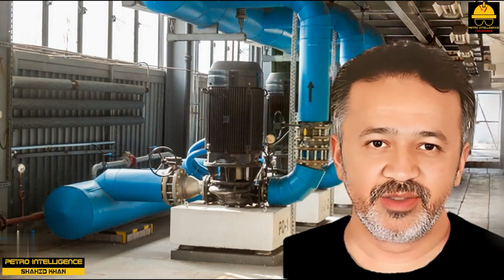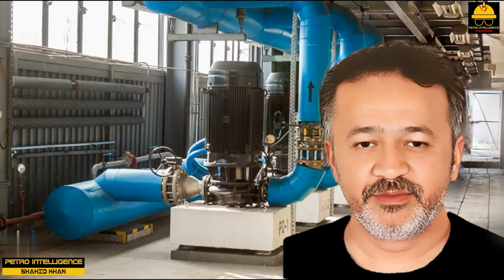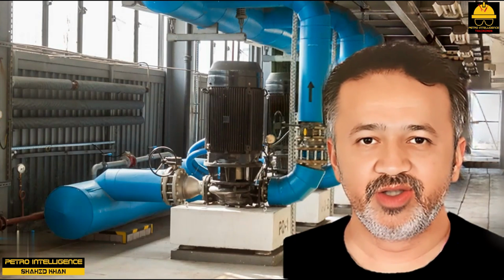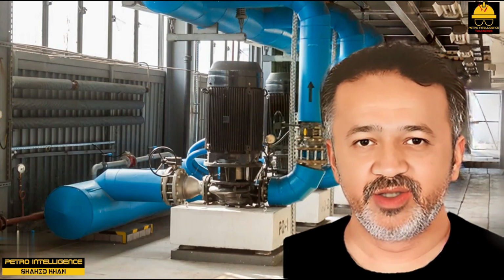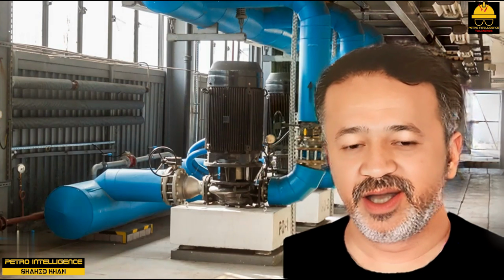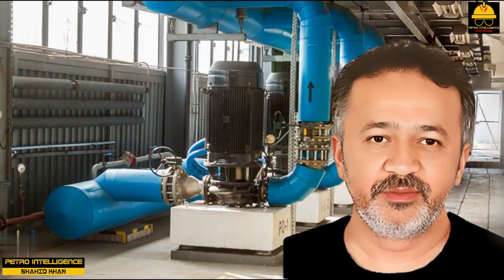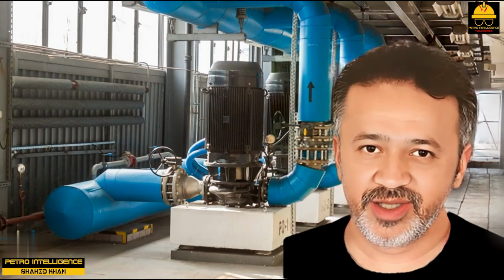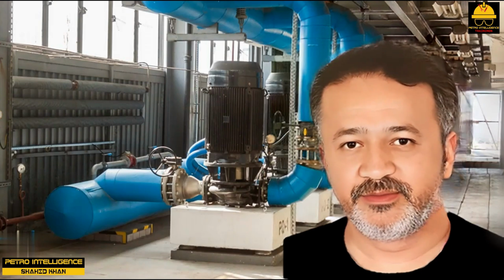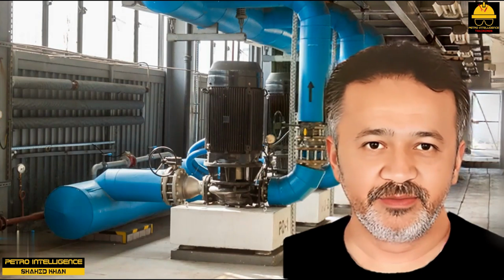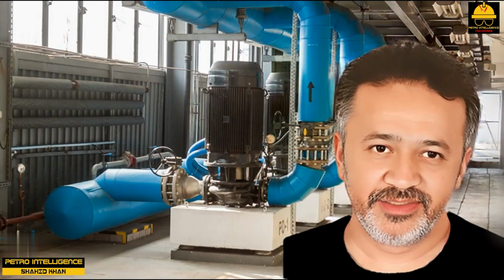For process people, the only practical method to check that a pump's seal and bearings are suitable for the larger impeller is to check with the manufacturer. Drilling pressure balancing holes in the hub of the impeller helps to reduce the extra strain on the bearings of a larger impeller. Sometimes installing a full-sized impeller causes the pump to vibrate.